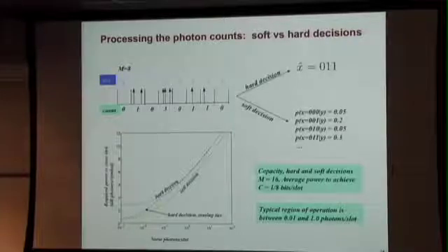You should compute probabilities associated with that event versus what you thought you sent, versus all the possible code words you could have sent. And the decoder should then take advantage of the computed probabilities rather than saying, well, I'm going to convert this to pulse and this to not pulse right away.